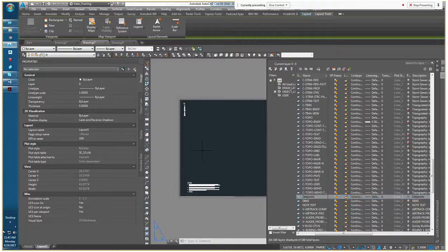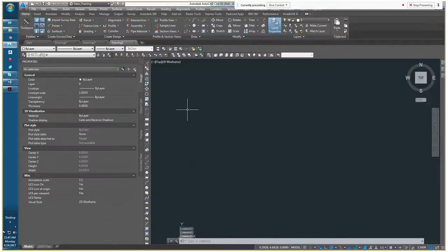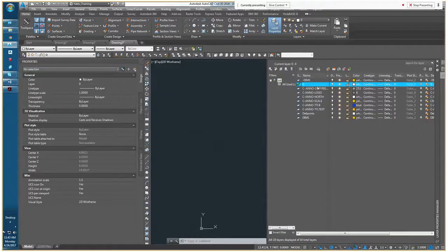Okay? So if we move over to drawing 3, which we started from the detailed DWG, we'll notice a few differences. One is it starts out in model space. Two, there's a very small number of layers in this list. I think 9 total, 10 layers. All right, 0 is a default layer, and def points is a default layer. The rest have been generated by us for commonly used layers within our space.